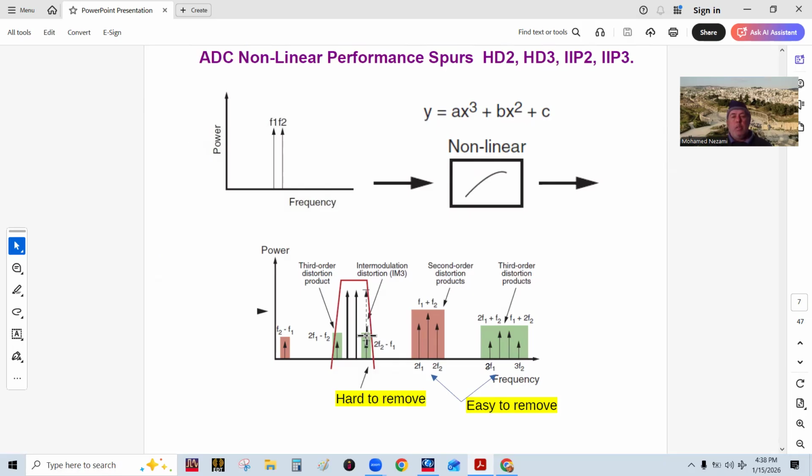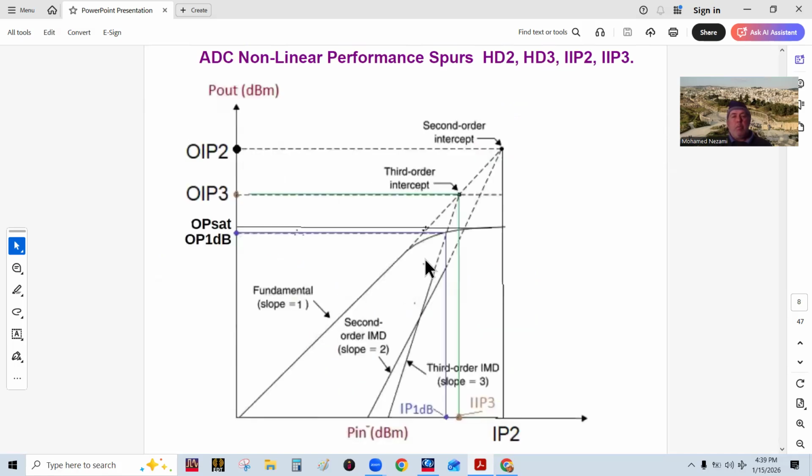there's a proportionality between the relative strength of the third order and even the second order intermodulations, and their strength is proportional. Usually, there is a relationship where one will increase 3-to-1, and one has a 2-to-1 relationship. Okay, and that has to do with the fact that you increase F1 and F2 by 1 dB. How much is this going to increase? These terms in here,